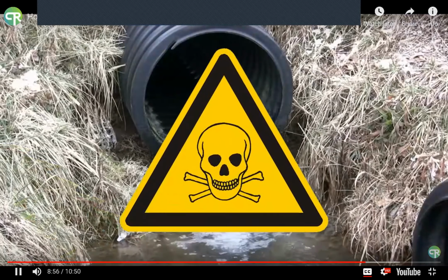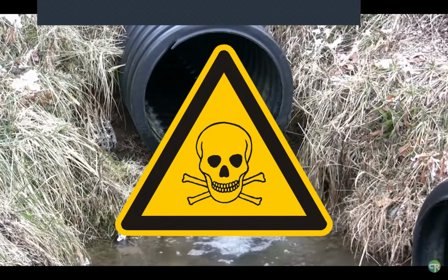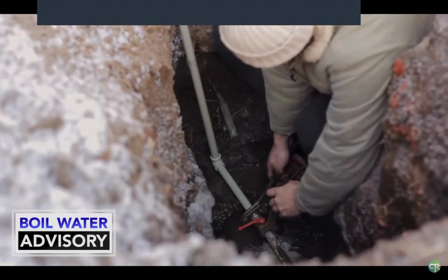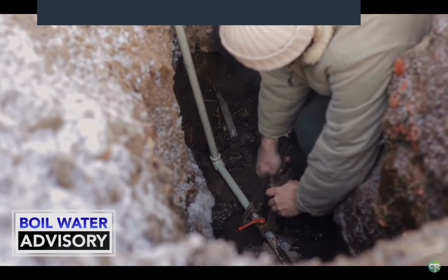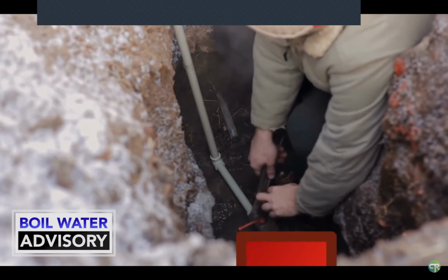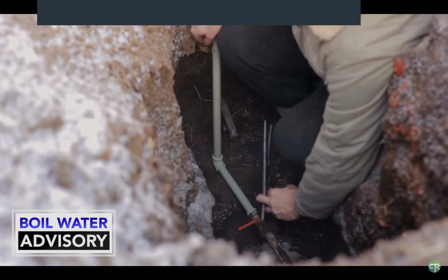This would contaminate the entire system and is one reason why you might experience a boil water notice. Essentially, that means engineers have reason to believe that somewhere in that city's pipe network dropped below the required PSI and water or contaminants might have infiltrated the system.